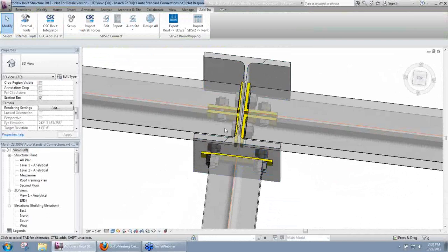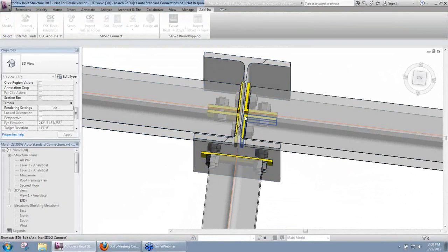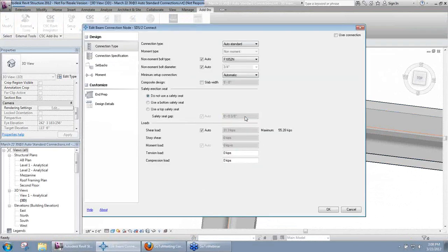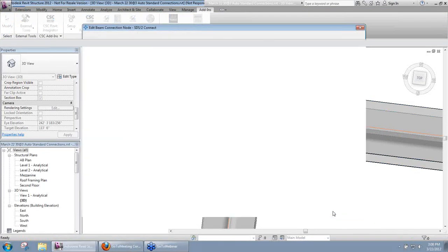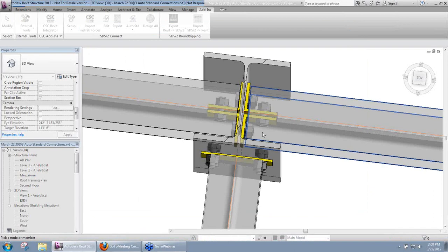am only affecting the beam framing to the flange, I'll go ahead and edit one of these to the web, just like I did to that one to the flange, and when I clicked OK it was redesigned. Same case here. However, that's not changed because it's a different scenario. I didn't change the scenario for the wide flange beam to wide flange column web perpendicular. Okay.